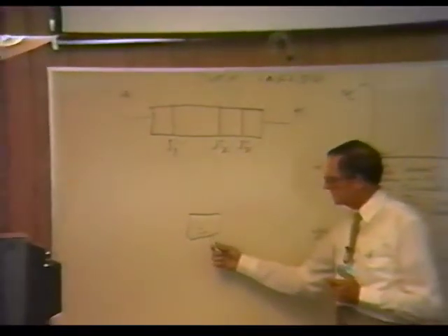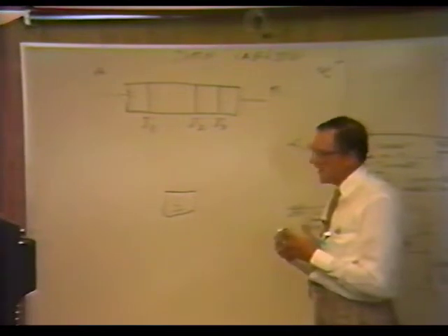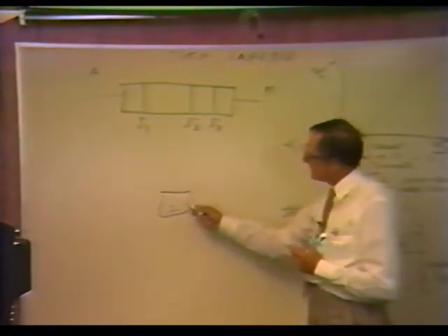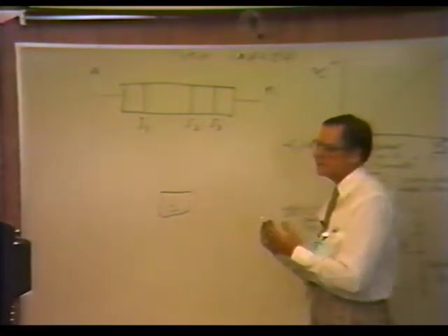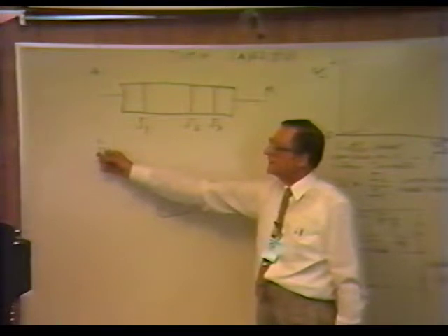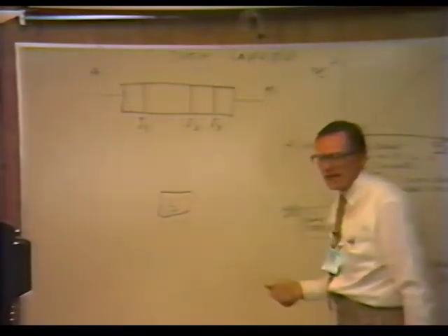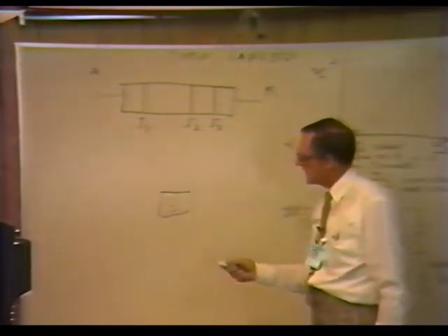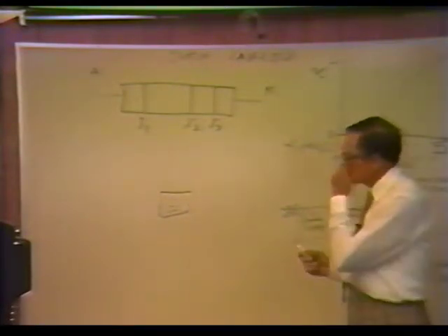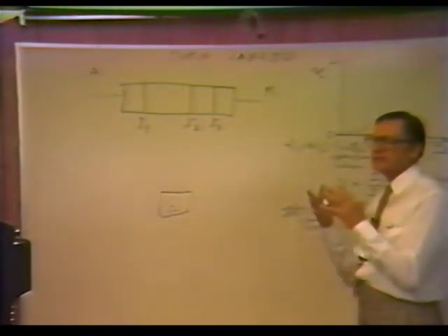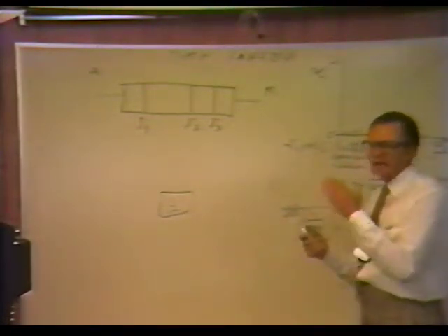It is a semiconductor. And now to provide some control on how that conducts and how we use it, we dope this silicon with impurities to provide carriers. Just as we provided in the thyratron, we had the gas, or the neon gas and the light, to provide carriers, and we had the electrons coming off the cathode. We need to provide some kind of carriers inside the silicon, so we dope the silicon. Now, the more impurities you put in, whether they are donor atoms or acceptor atoms, the higher the doping level.